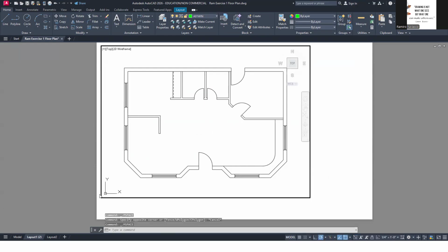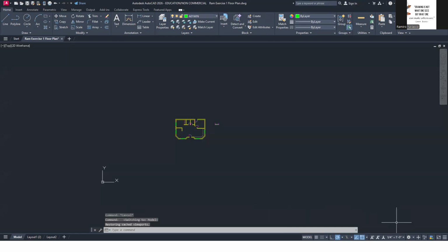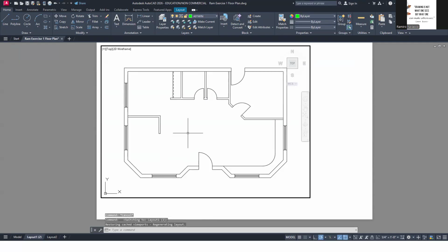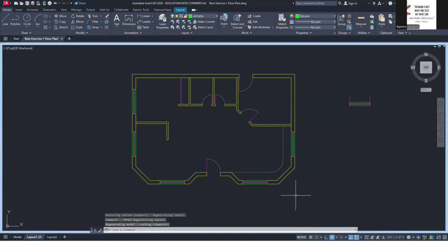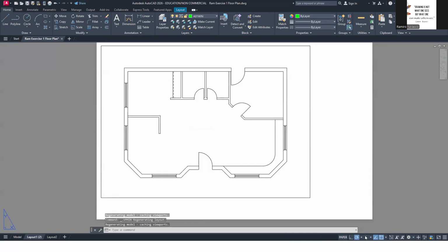Here, the same as what you're using here. So 1/4 is to 1. So in model space, you do 1/4 is to 1. Now, to make it a little simpler, while in paper space, you can maximize the viewport. So it's as if you are in model space in the model tab, but you are actually in the layout tab. So you can also go back and minimize it.